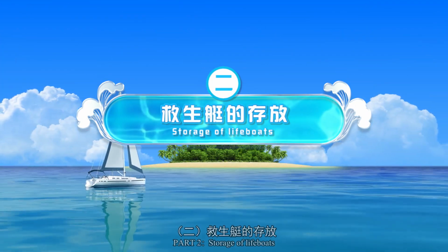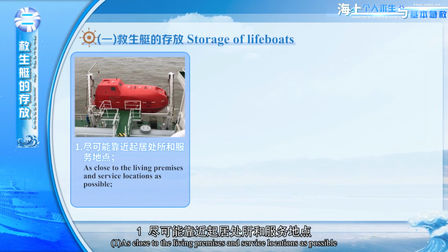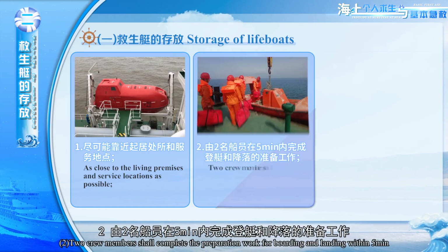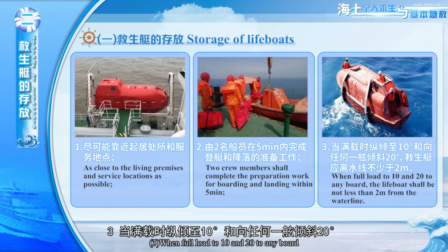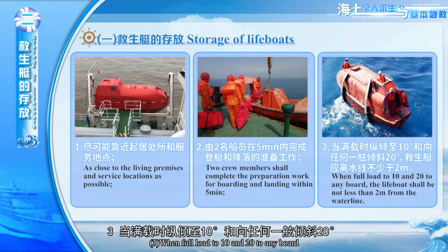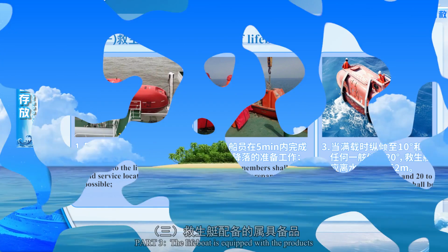Part 2. Storage of lifeboats. 1. As close to the living premises and service locations as possible. 2. Crew members shall complete the preparation work for boarding and launching within 5 minutes. 3. When fully loaded, the lifeboat shall be not less than 2 meters from the waterline.